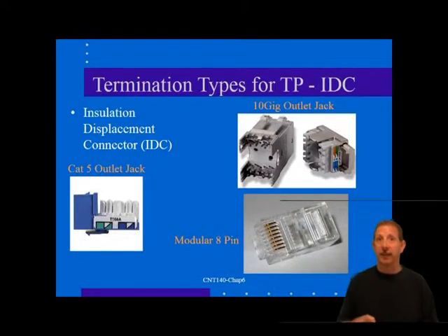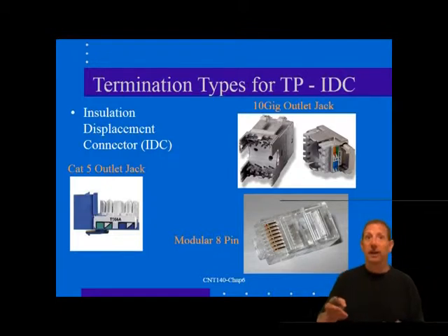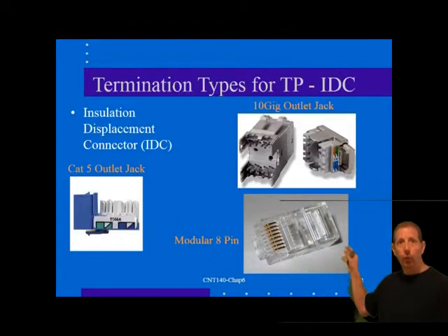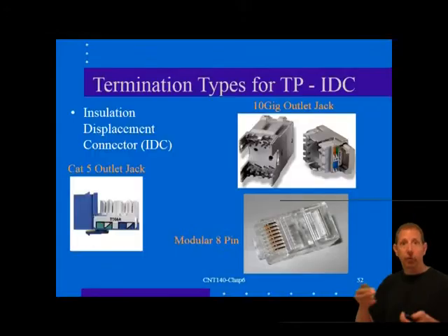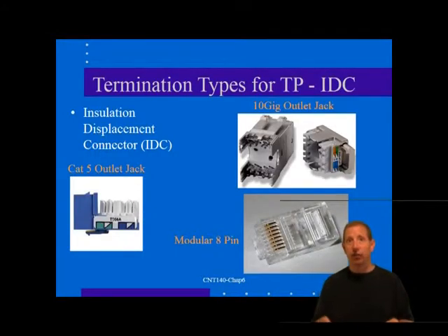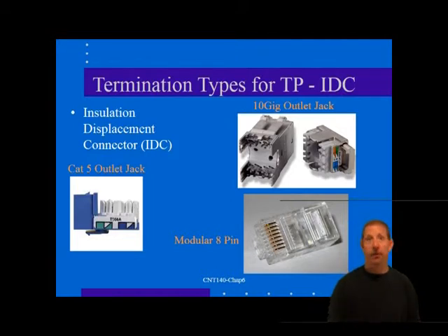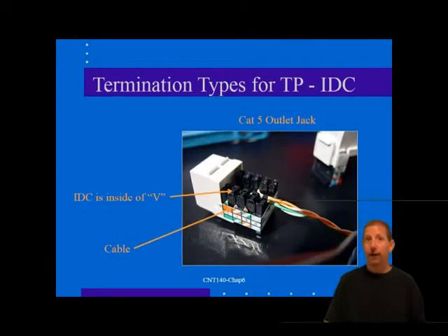Another type of IDC jack contact incorporates the newer 110 type punch-down strip, as shown here behind me. Now, the 110 strip may be separate from the modular connector and connected by wires as with the 66 type jacks, or it may be an integral part of the connector module. If discrete wires connect the strip, the same untwisted wire problem exists as with the 66 blocks, and certification above Cat 3 or 4 is then rare.